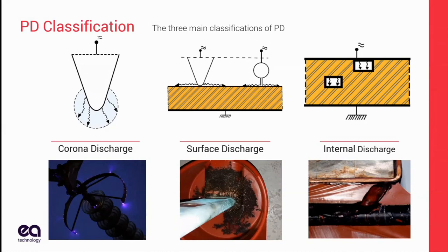The second, which is the most common and the fastest moving, fastest growing partial discharge, is surface discharge. This is characterized by the current path being the interface between the insulation and air. As you see here in this picture, and this is 6-year-old switchgear, you get this tracking across the surface. What we saw in the video in the last slide, that surface discharge, the current is trying to find a path to ground. While it's doing that, it's damaging the insulation. It's leaving a carbonized track behind it.